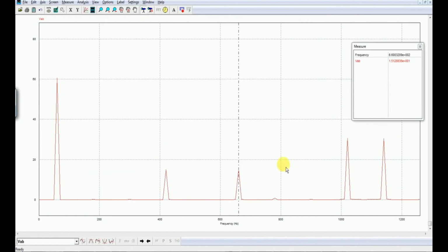So if I go here and make it all the way to this particular point, this is at 1020 hertz, and this 1020 hertz is actually the 17th harmonic. The amplitude VAB is equal to 30.6 volt, and thereafter we should see f19, which is the 19th harmonic. It should appear at around 1140 hertz, and that is also equal to 30.528.